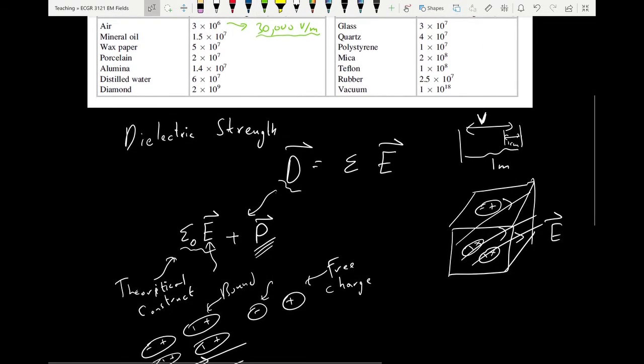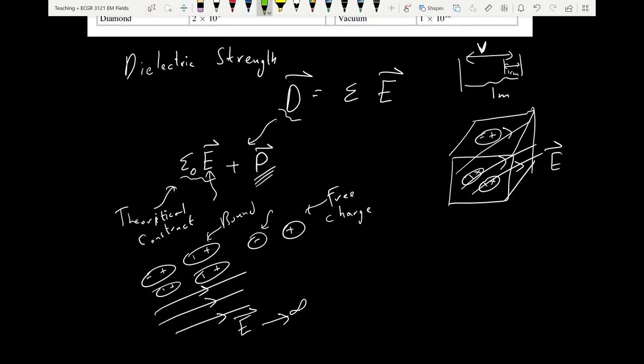One application where you see this being important is in PCB design. If you're designing a PCB board with a bunch of components on it, and let's say hypothetically this board is handling voltages of 1,000 volts, right? That tells me that even the air matters. Even though I have two components with air between them, I have to be careful with the distance between those two components. This is called creepage and clearance.